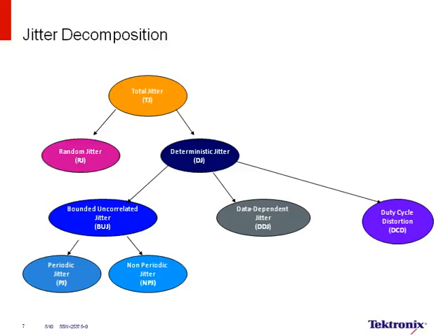Okay. The next question here is, when setting the clock recovery parameters in a scope, what are we trying to match? The silicon PLL on the receiver side, the CDR loop parameters, other? So the answer is, when you're trying to set the clock recovery parameters in a scope, you are trying to match the receiver silicon.